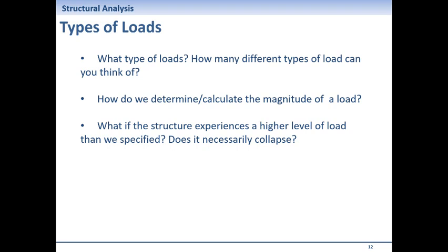Because for an individual engineer, it's really difficult to calculate how much live load we are going to consider here. So these all come from relevant standards. So we refer to a standard, and we'll see some examples. There's a table. It tells you if you are designing a classroom, this is the live load that you need to consider. What are the kPa?